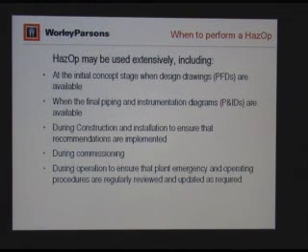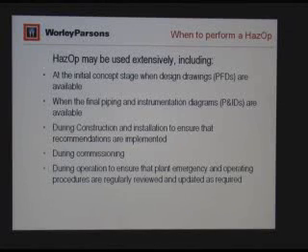The other time is when the final piping and instrumentation diagrams are available, when the design is somewhat firm, so we know what kind of instrumentation and safeguards we already designed into the system, then we analyze. And at this stage, of course, we can design the process safer and avoid incurring a big cost of any process change, because no equipment is supposed to be purchased. Design is not set until you go through the HAZOP.